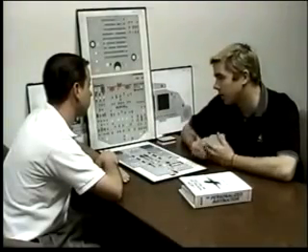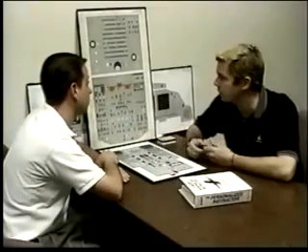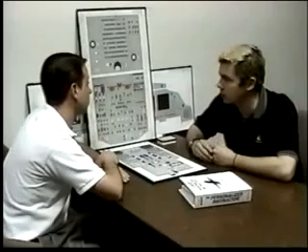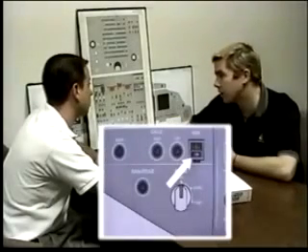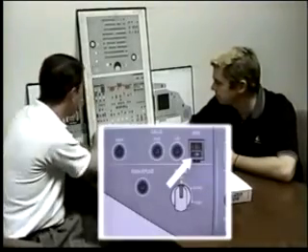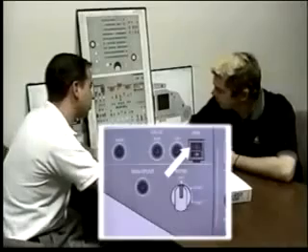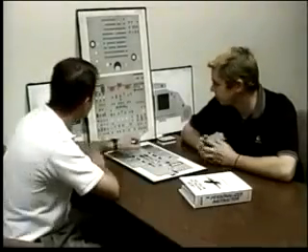Unfortunately, on this airplane, we can't conference call by using the forward and aft calls, and when they call me, we can't conference call. Really, the only way you can conference call with the people in the back is by selecting emergency to on. That'll give 3 dings in all the stations, and they can all get on and talk as a conference. What if you were to get the amber call in the emergency switch? That means that they are emergency calling me from the back.